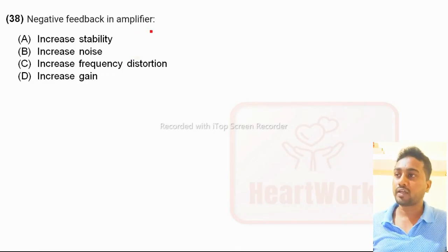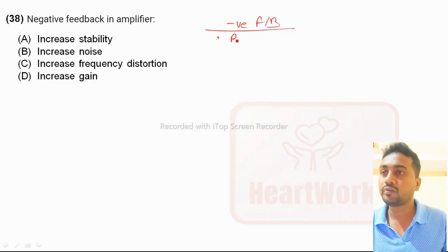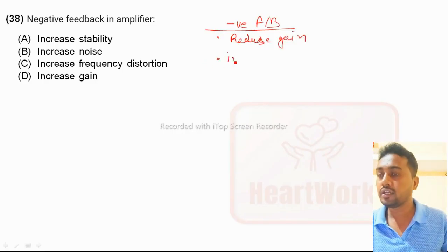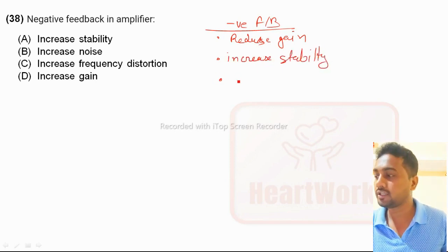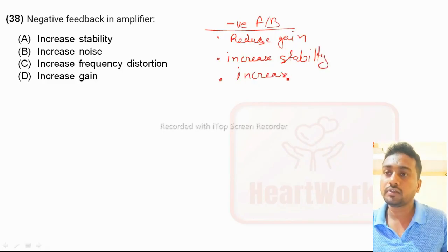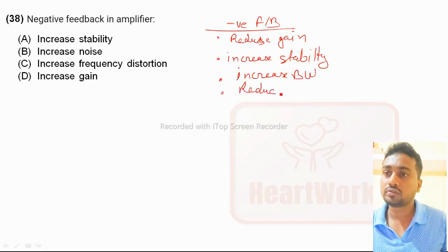Negative feedback amplifier. If we talk about the properties of a negative feedback amplifier, it reduces gain, increases stability, increases bandwidth, and reduces distortion.